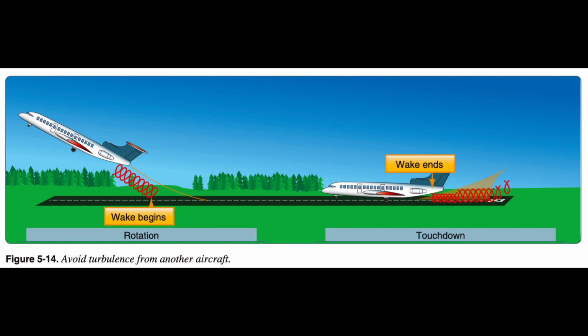A hovering helicopter generates a downwash from its main rotors similar to the vortices of an airplane. Pilots of small aircraft should avoid a hovering helicopter by at least 3 rotor disc diameters to avoid the effects of this downwash. In forward flight, this energy is transformed into a pair of strong, high-speed trailing vortices similar to wingtip vortices of larger fixed-wing aircraft.